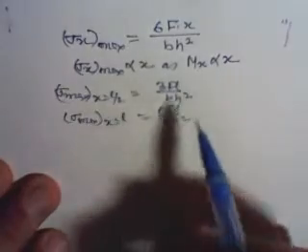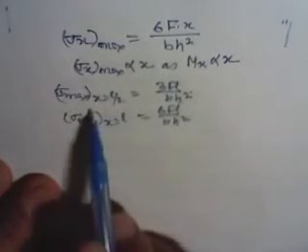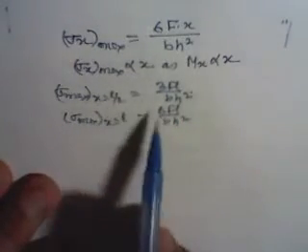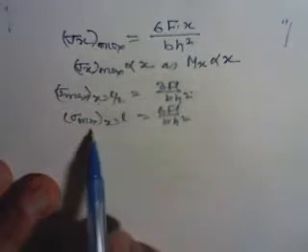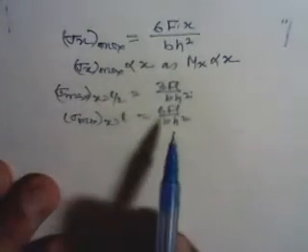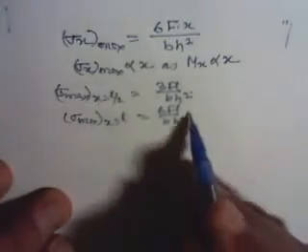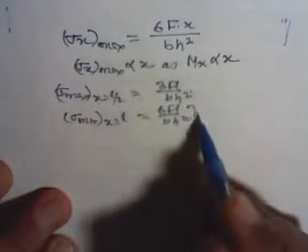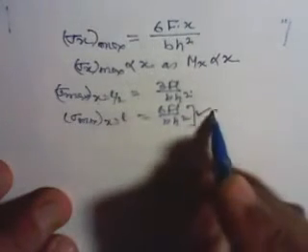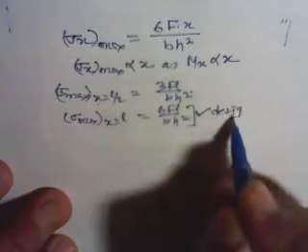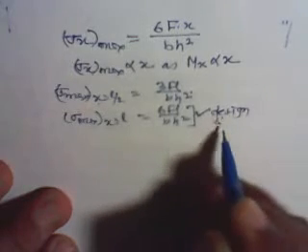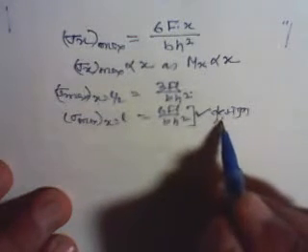So sigma X at L by 2 is half of sigma X at x equal to L. We will be designing a cantilever on the basis of this. This will be used as design stress, the maximum induced stress in the design equation.